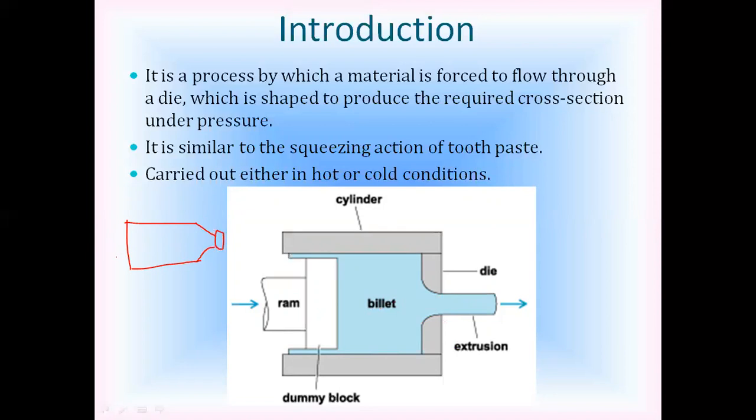So we apply force, and we call this force a squeezing action. The same action is done in the extrusion process, which is why we take the example of toothpaste. The process is similar to that of toothpaste: once the force is applied through the ram to the dummy block, the billet is pushed towards the die.